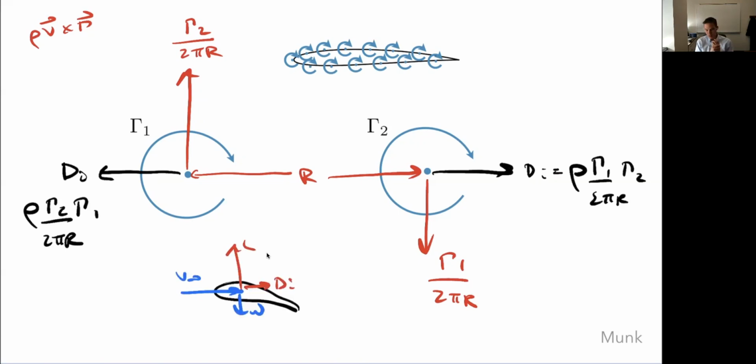Okay, so that's really the last idea here. And this does mean that this formula here is quite general, even though we've derived it under some very specific case with just a straight wing. This is a general formula we can use, and very useful. We don't have to use lifting line theory to compute this per se. So as we'll see, we'll just compute lift and drag with other methods like vortex lattice that we'll talk about next time. And we could then look at our Oswald efficiency. Elliptic has an Oswald efficiency of 1. That's our minimum drag solution.